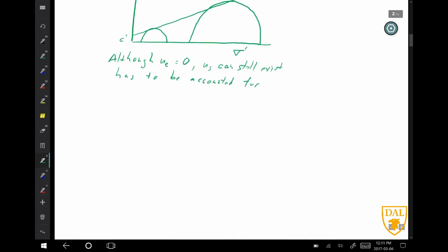Okay, for example, if you have a soil and the water table and you're located at some depth below it, okay, you have a hydrostatic gradient, gives you the static water pressure at that point. But we're assuming that any loading that happens, the excess pore pressure is 0. Okay, so US plus UE, which goes to 0.